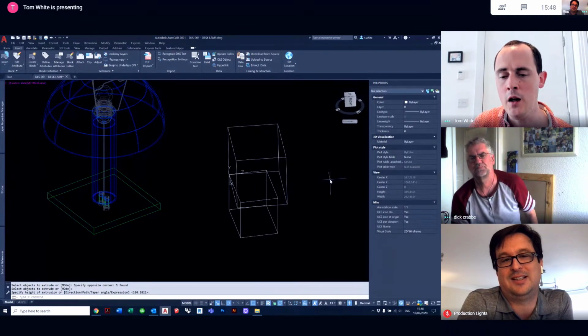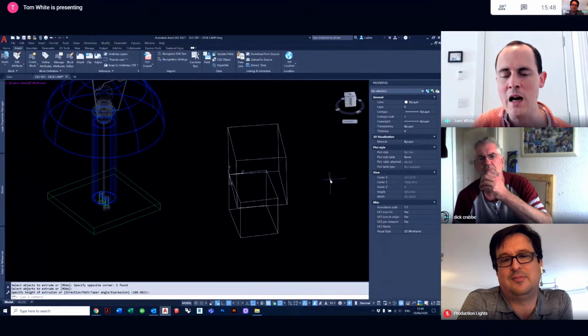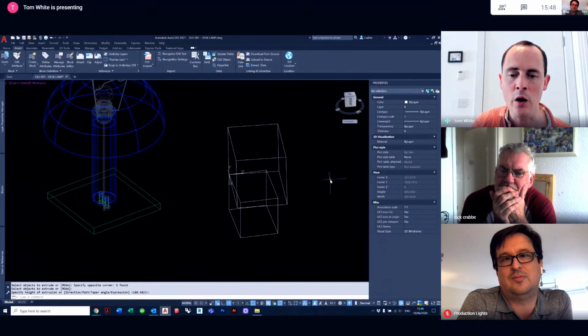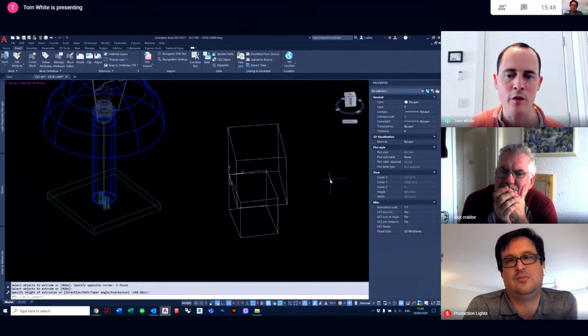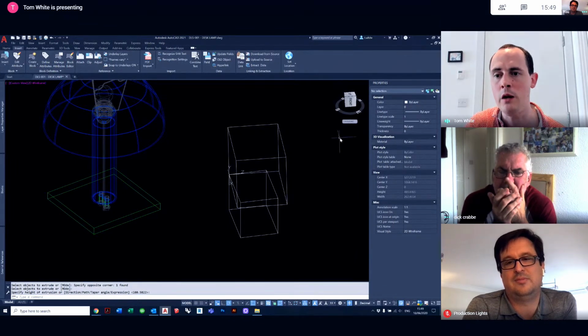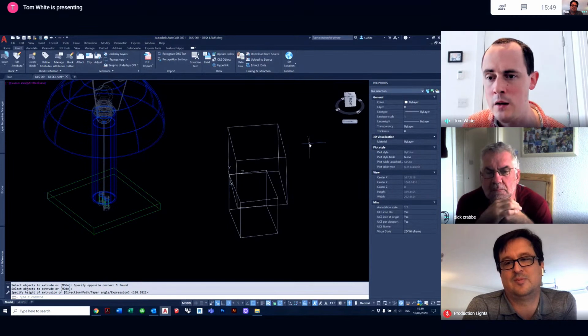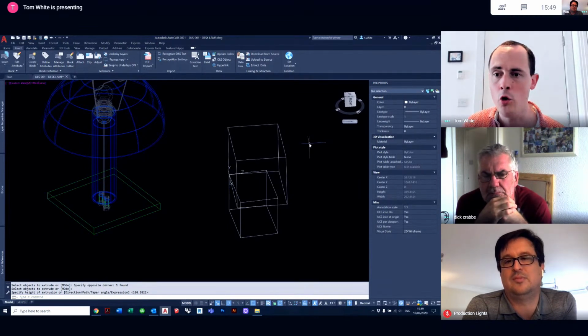One thing that I feel at a glance, if I was to open this drawing, it wouldn't be totally obvious, but there'll be a few hints that something's happened to the UCS. One of the biggest hints is the view cube, I believe it's called, in the top right-hand corner, has gone a bit weird. It's saying that what should be top is left, and front, I suppose, is kind of right. But something has happened there, and I need to try and rectify it.